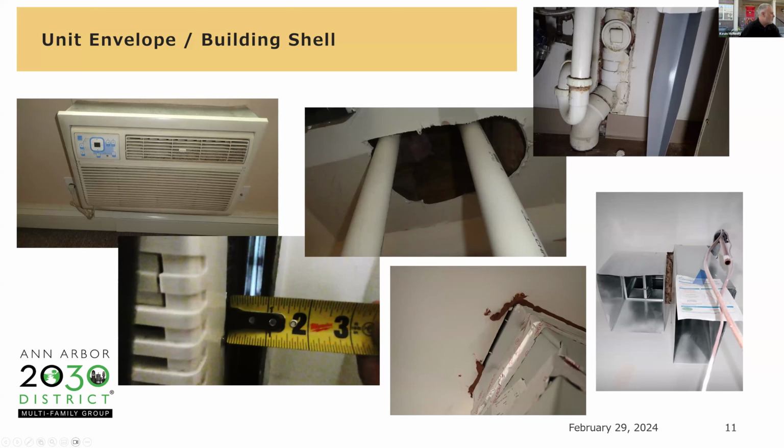Then in the envelope, a lot of older buildings have window unit air conditioners that are mounted in a sleeve. These are extremely leaky at the unit as a whole. And then here, in this picture with the tape measure, you can see in the back, that's daylight back there. And the sleeve itself, they did a good job of centering it on the left and right side, and the top, it was a uniform 1 inch all the way around, allowing air to flow in. We can use a backer rod, that would probably be the easiest, going all the way around that to stop air leakage.